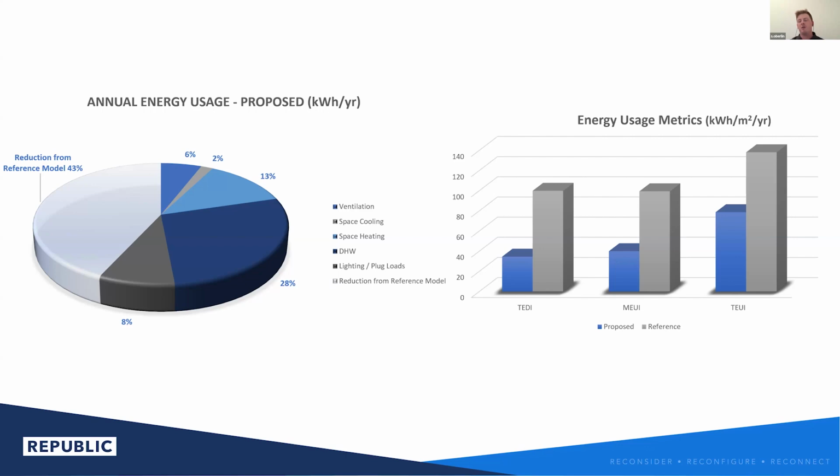So we did wall simulations where we looked at anywhere from 2 inches of outboard insulation to 12 inches of outboard insulation, and tried to really understand where made the most sense in terms of thermal energy demand for the building and how that was shaped by the exterior insulation.